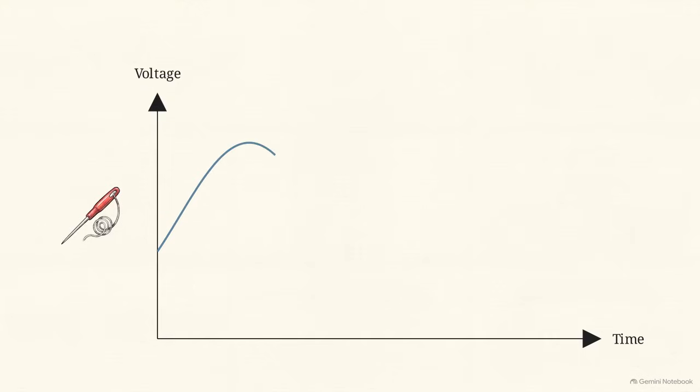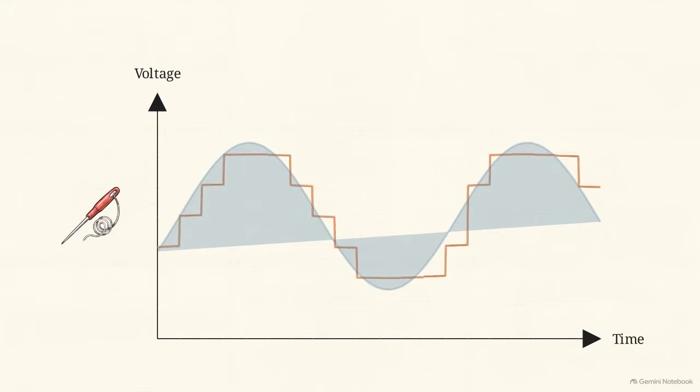This diagram shows how the converter maps a continuous voltage curve into discrete countable steps by slicing it vertically and horizontally. The STM32 features a 12-bit ADC. That means the hardware is designed to divide the continuous incoming voltage into exactly 4096 distinct levels.